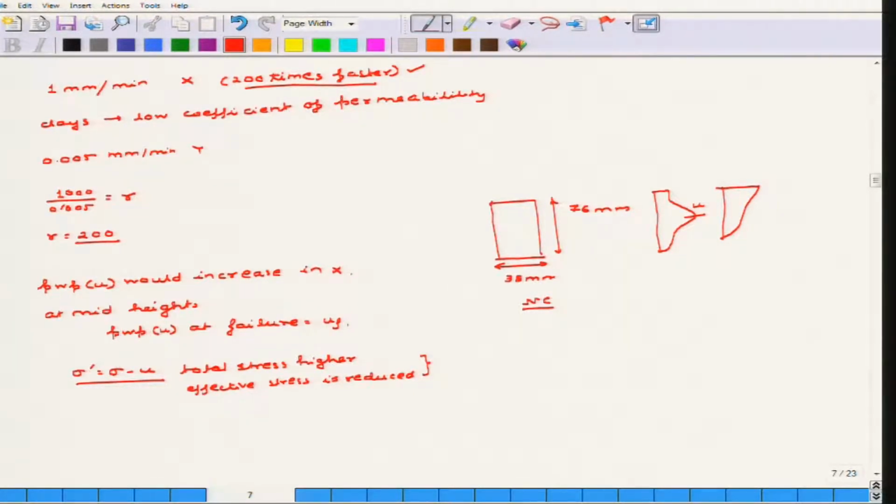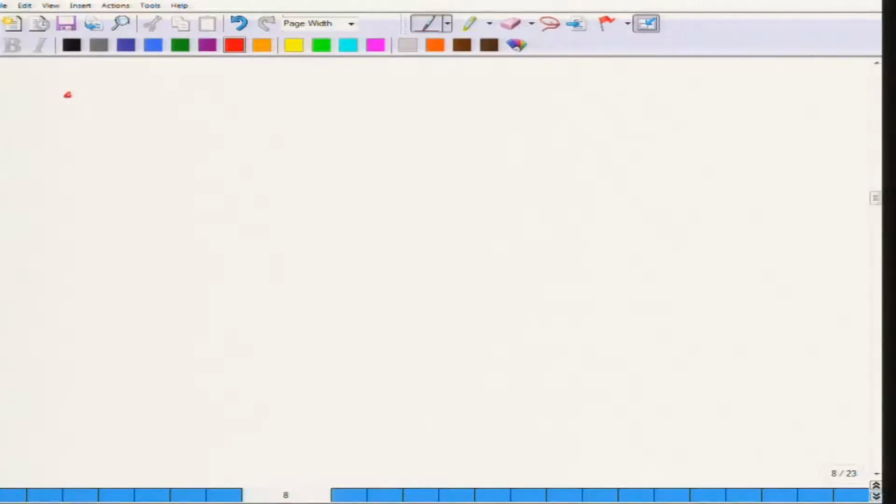So obviously you have to plot the Mohr circle with the effective stress, because you have to get the effective parameters. The effective parameters are more important than the total stress parameters. We have seen that from consolidation itself, because whenever you are supposed to find out, let us say, the settlement delta S, or the shear strength tau f, you are always considering the effective stress parameters rather than the total stress parameters.